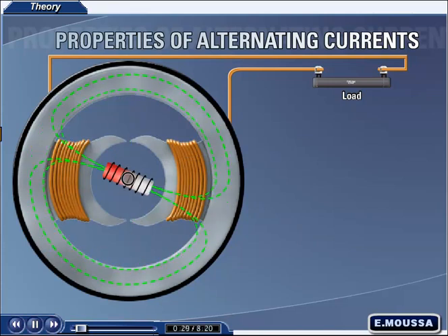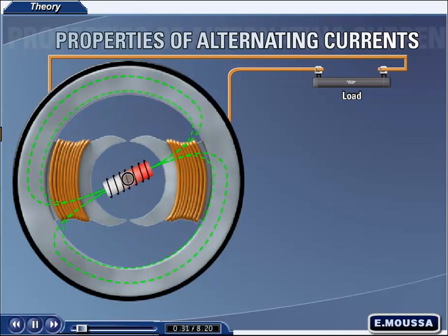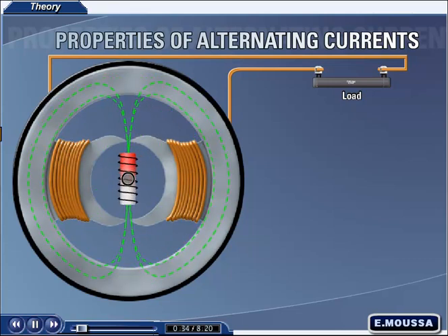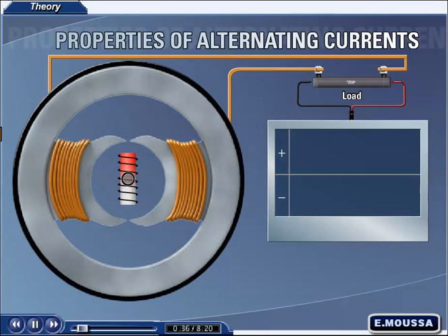When a DC current flows through the windings of the exciter, a magnetic field is formed. As the exciter rotates about its axis, its field will cut through the windings of the stator, inducing a voltage in the stator. Let's plot a graph of the voltage induced in the stator windings on the y-axis against time on the x-axis as the exciter rotates through one revolution.